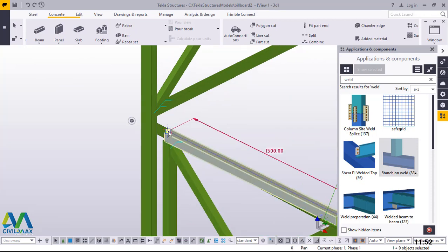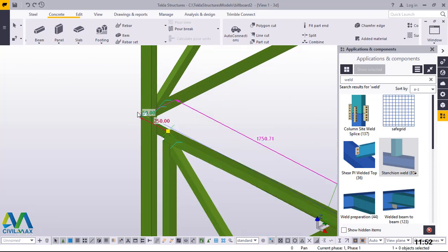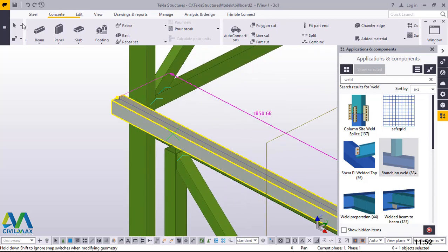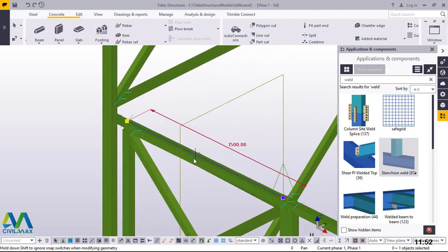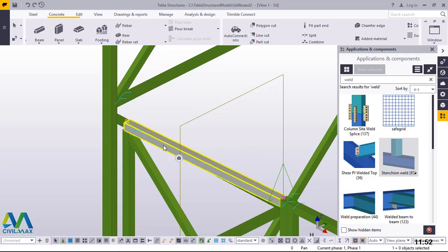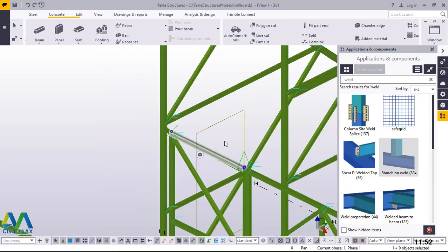What we can do, just drag it out to that position, but that will not be accurate. That's why I'm using this trick. Click on the part you want to extend or reduce the length. Click on that, click on it, then mouse over it, then click on the dimension, click on the direction you intend to increase or reduce, and I'll delete that. I'll give it 1800 and enter the keyboard to see where it will reach.